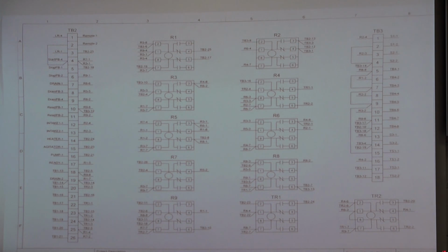And the reason for that is it's built into it. Those coils, as soon as you remove power from them, don't go from red hot to cool. They gradually cool off. And that's a timing circuit. So when you cut it off, there's still heat there, so let's not waste it. It'll keep your fan blowing a little longer to take advantage of that heat that would otherwise be trapped.